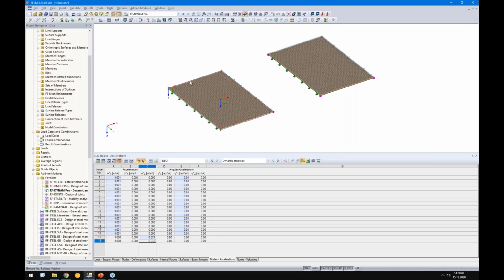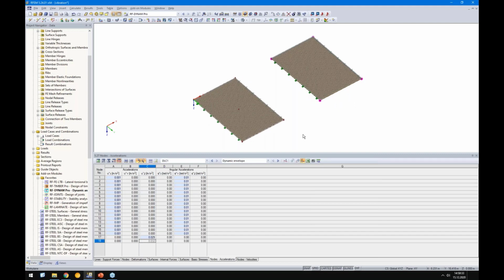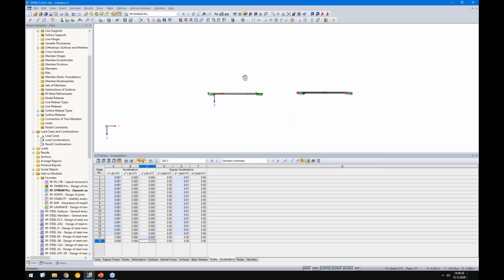And of course, you can add the supports here and here. So support it on 4 sides and run the analysis, copy the angular frequency again, insert it in the time course monitor, and then you will get exactly this 0.065 meters per square second. But this is your homework, and for me, that's all for today. I hope everything was clear with this approach and with defining the contact solids and the surface releases. It's a mighty feature.